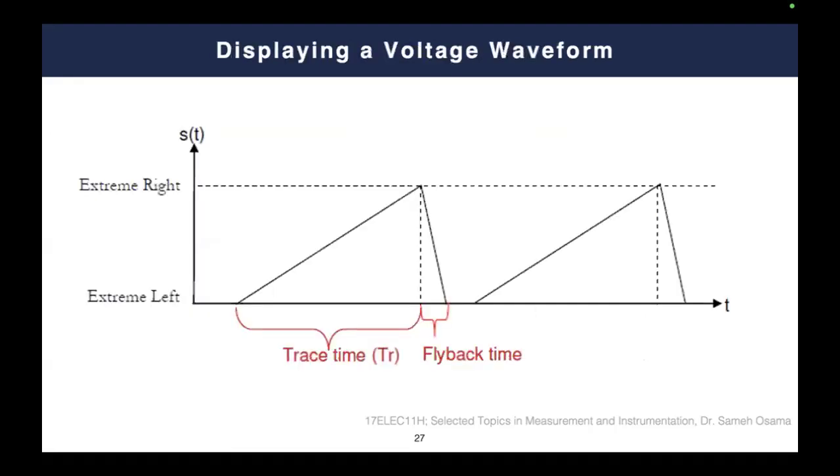That's why we have to make this flyback period as the guard band in between, as you see. So this stage should be in a very, very quick manner, as if your eye cannot observe such variation. This is a very important feature you have to manage while you are designing your oscilloscope. So here, the target is to minimize this time as much as possible so that your observer cannot recognize that you make this flyback period and you start a new cycle.